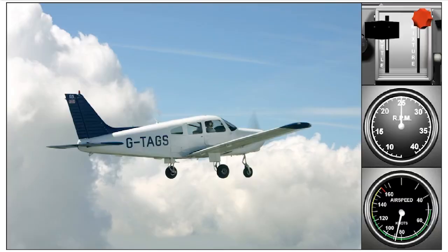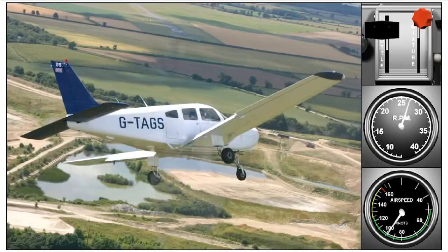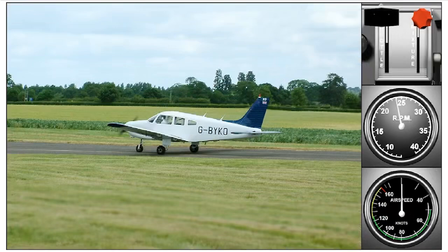When a fixed pitch propeller is being driven by a piston engine, the RPM is dependent on both the power setting, throttle position, selected by the pilot, and the true airspeed of the aircraft. It would be possible to overspeed the engine in a dive if the throttle was not closed. Conversely, with the aircraft stationary on the ground, it may not be possible to achieve rated RPM with the throttle fully open.